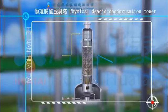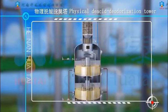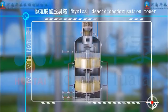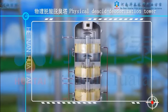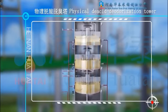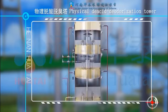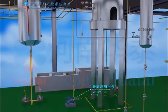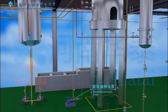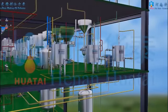The physical deacidification and deodorization tower structure combines the deacidification tower and the deodorization tower. After the secondary deacidification on the top, the oil flows to the deodorization tower at the bottom. The pump ejector design inside the deodorization tower promotes the oil and the steam to fully contact to separate the light constituent gas from the oil in the high vacuum system. The deodorization oil is then transported to the oil screw plate heat exchanger by the extraction pump to exchange heat.